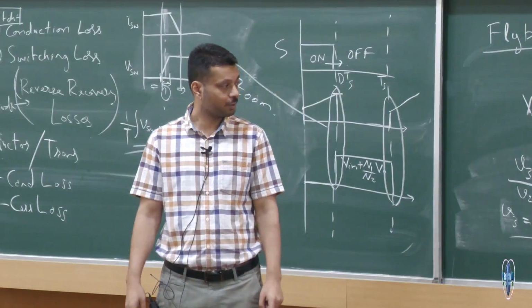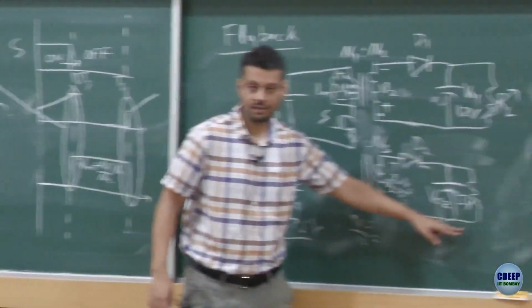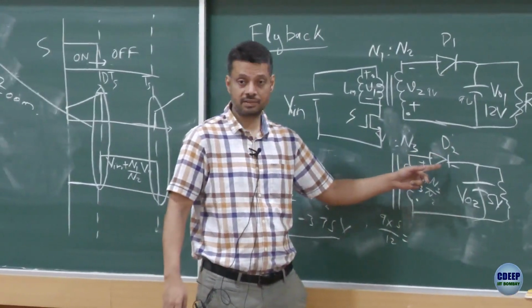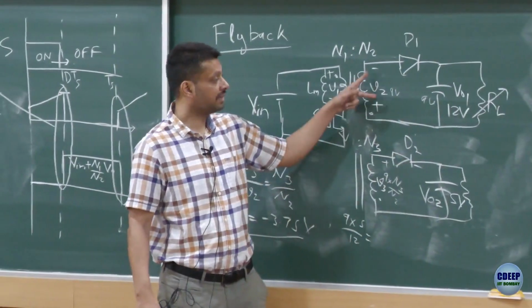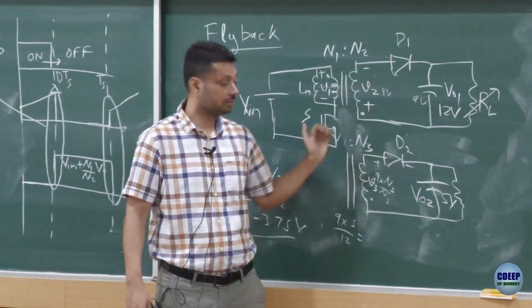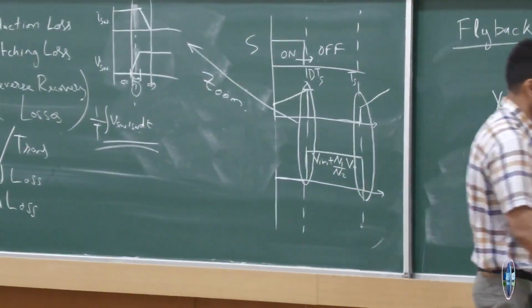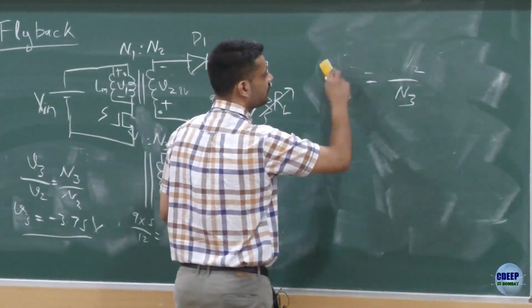It is possible with lower voltage also, same thing, 5 volt goes to 4 volt, right. Assume this diode conducts, this becomes 4 volt, to find this voltage here you will get 11 volt, this diode will be reverse biased, so everything will flow here. Yeah, you can do that, okay, good. You guys know a lot of things, very nice.